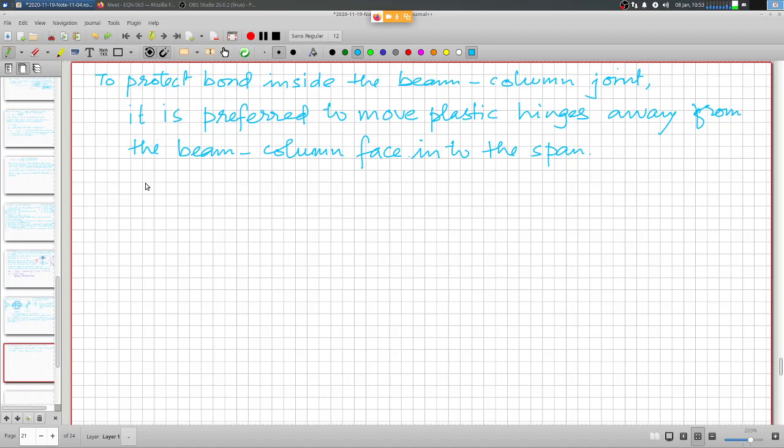The design, whatever you have worked out as a presumably strong column, weak beam, will continue to behave in the same way as strong column and weak beam, and inelastic deformations will only happen in the beam some distance away from the beam column face, and that will be manageable, so to say, repairable damage, and all should be well.